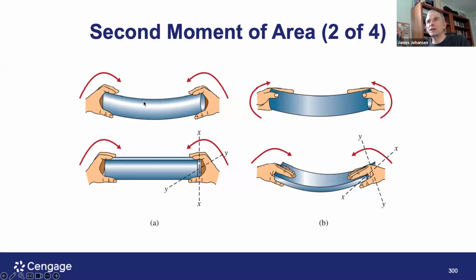And so you can be thinking of a tube, say like you have some PVC pipe, some basically plastic, you can bend it to a degree. If it was metal, it's going to be a little bit harder. If you have another piece of structure, so you can see here, you're actually bending it in the thin axis and you're getting more, there's more ability for you to be flexing it, versus if you try to do it the other way, it's going to be a lot harder.